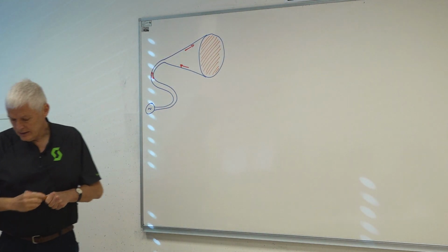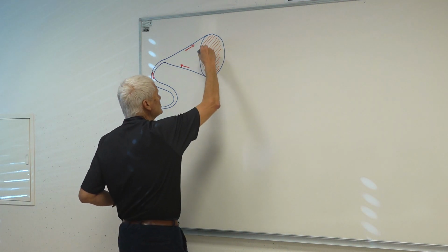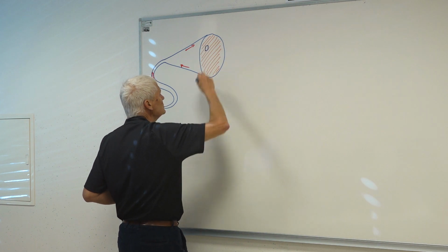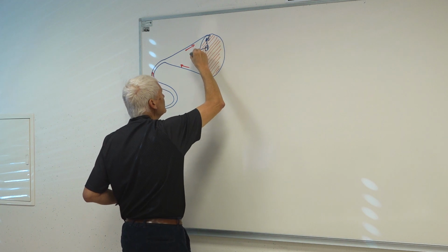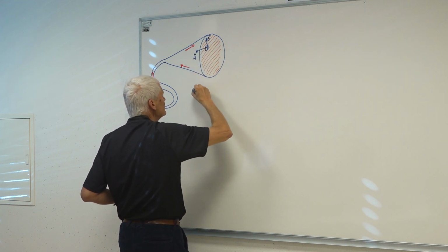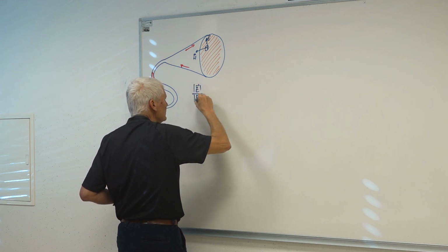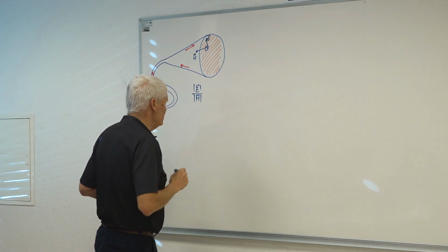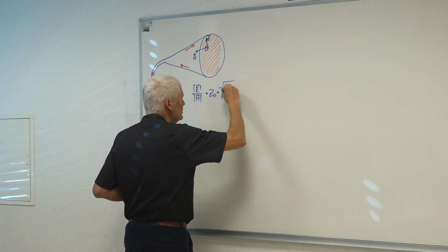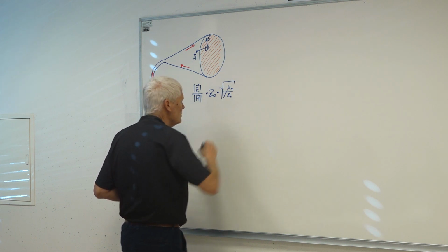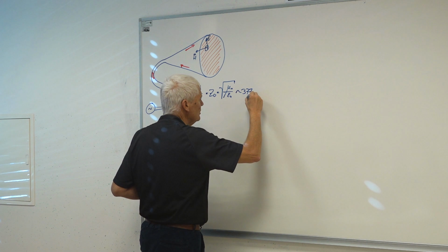And how to calculate the radiation? We introduced the Huygens principle with Huygens sources on this aperture here. Huygens sources that may have an electric field and magnetic field. And these two fields, I have to take just the magnitudes of the fields because I cannot divide vectors. Their ratio is equal to the impedance of free space. So this is the square root of mu divided by epsilon, and this is approximately 377 ohms.